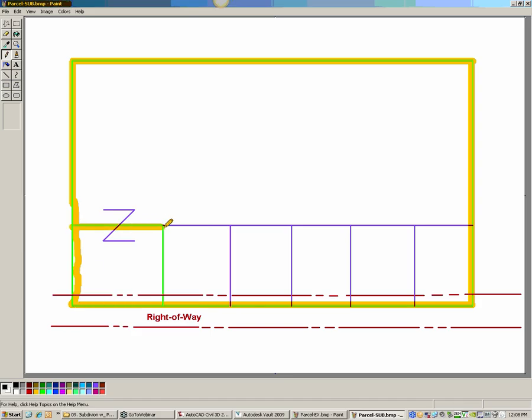And I would trace over this in the survey file. And then I would come back in my design file and I would draw in this design line work, splitting this into additional parcels along the roadway here. Now it's important that you do this in a separate file. First of all, you don't want to be changing the survey's existing conditions parcels. You want to make proposed parcels.